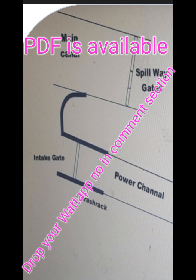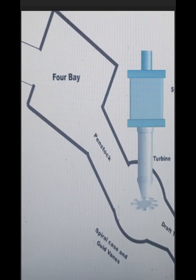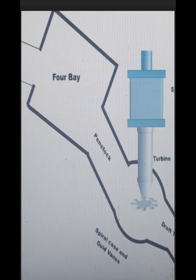Step 2. Power channel and forebay. The power channel holds the water which is used in power generation. The power channels for large plants are excavated type, and small powerhouses use concrete structure on the ground level. Forebay is the pre-storage for the penstock. Step 3. Penstock. Penstock is a large pipe which carries water from the forebay to the turbine of the hydropower plant.